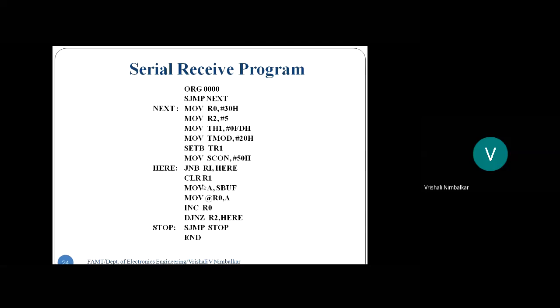Let it be a timer flag, or let it be a serial transmission flag or serial reception flag. Whenever we check the flag condition, make sure that you clear the flag and then proceed ahead. Right? So clearing RI is very important.